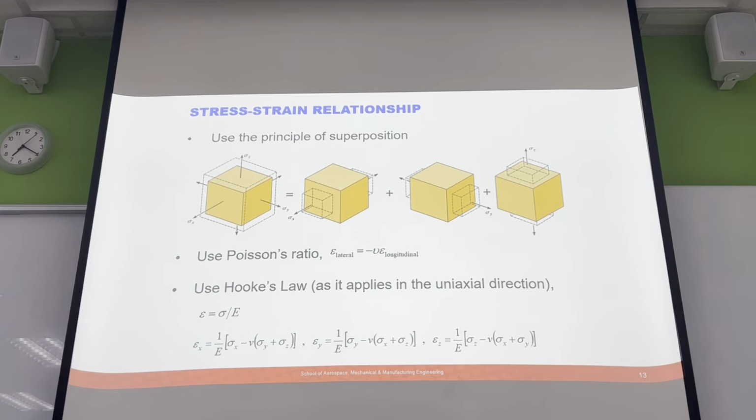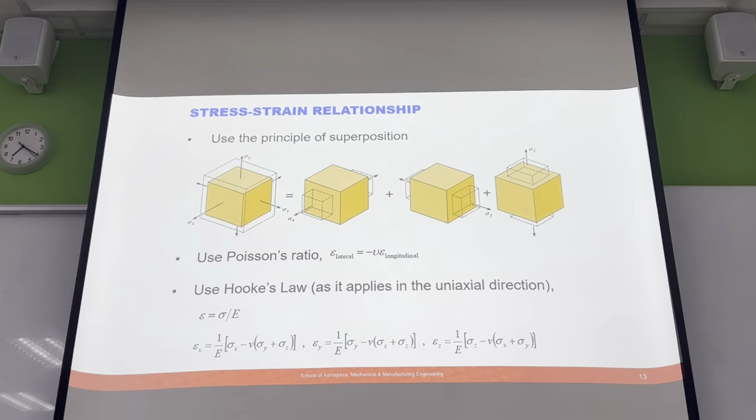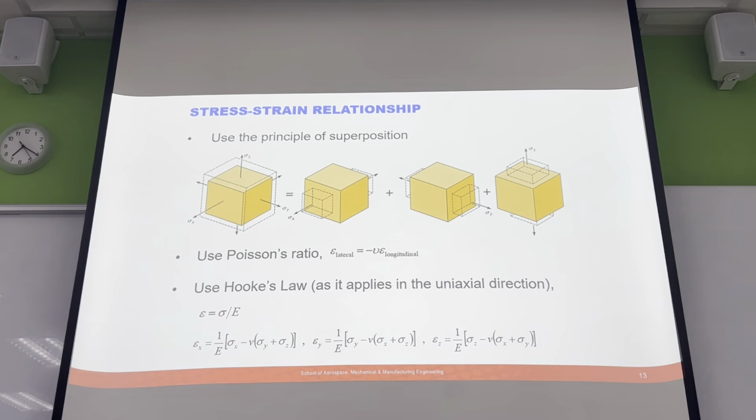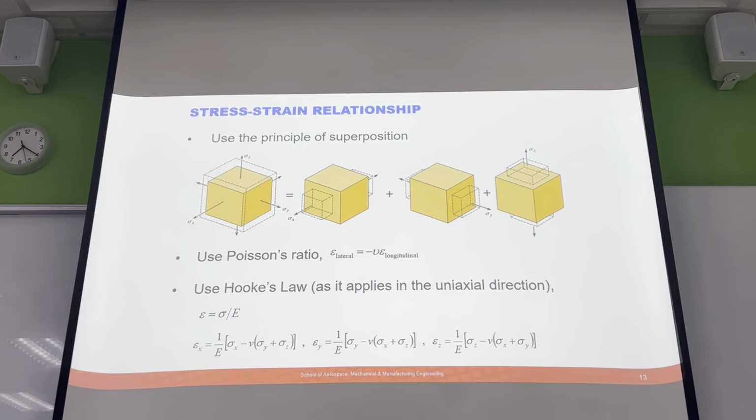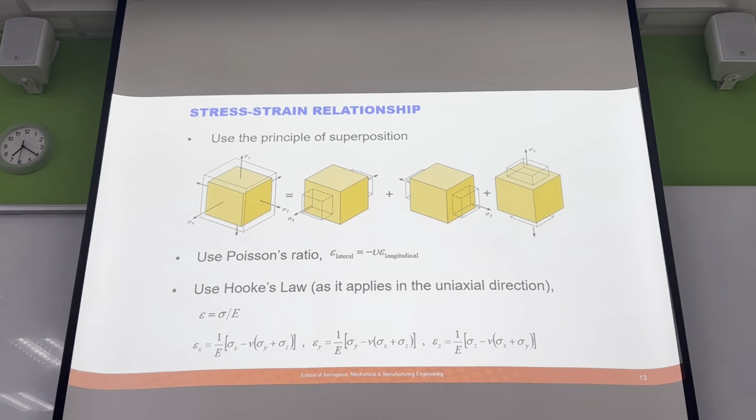If it's 0, they're more like foam materials. If the Poisson's ratio is 0, then we don't get any expansion in the other directions. So when you crush a foam, it doesn't sort of squeeze out. But metals typically will have, like aluminium has a Poisson's ratio of about 0.3 to 0.33, depending on its grade.